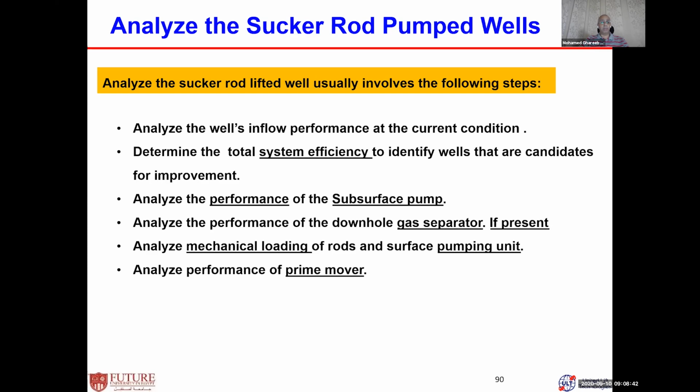When you design the system, as I showed you before, you need to start with your well inflow, the current well inflow and the predicted well inflow, because maybe you have a reservoir with some decline in pressure, some change in flow properties, whatever.